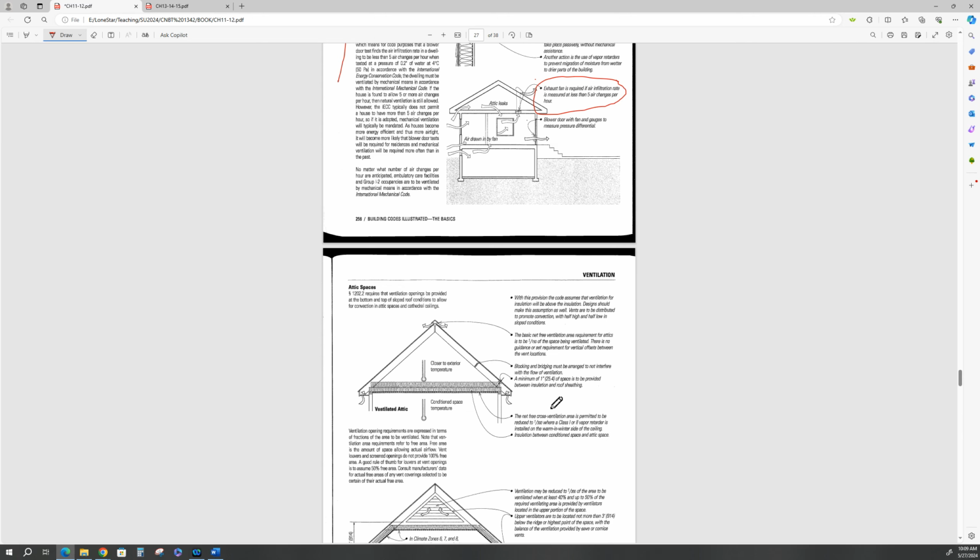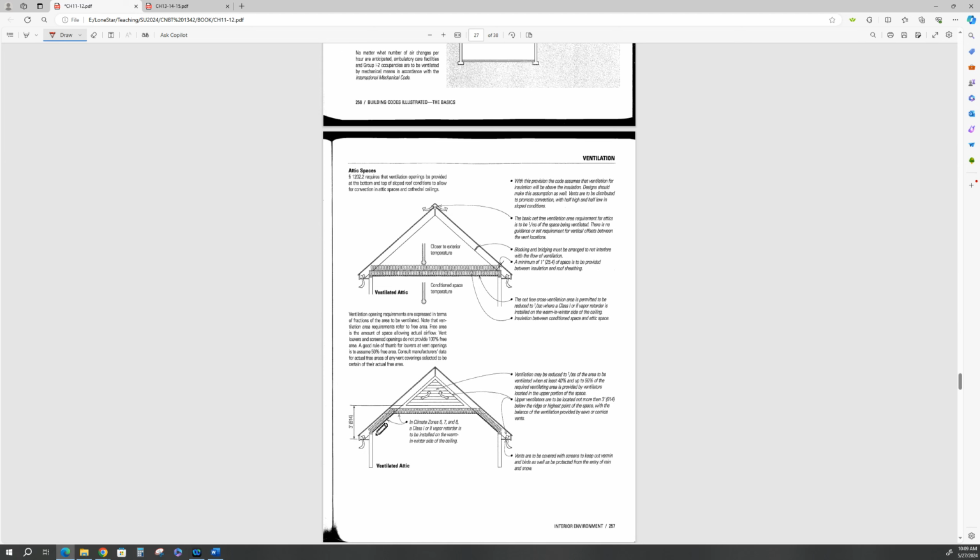All right, let's go to vent louvers. This is a vent louver, a ventilation louver. What is the free area of a vent louver? For vent openings covered with screens in attic spaces, the net cross-sectional area is permitted to be reduced to 1/3 of the 1/300ths.